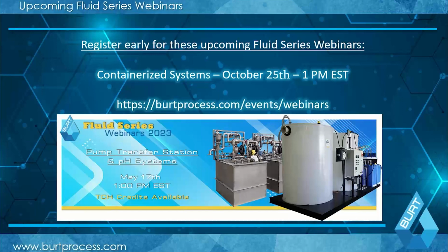Just to follow up on a reverse of that, there's another way to look at this, whereby you have a line coming that needs to be pumped to a pH system. That line's 7 feet underground, or you're basically below grade. And then you have the trade-off conversation, which you could do both ways: do you put a lift station fitting on the cover, and then your pumps are 7 feet below grade, or do you put the pumps on a skid above the grade, which is the tank down there, and you have a self-priming design, or do you actually increase the tank height all the way up, and then you have a side inlet fitting? And I've done all three different ways.